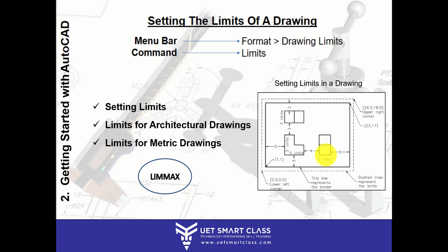Let me give you another example. Say you are drawing a 50 yards plan of a particular house or a flat. If you are drawing your other drawings for a 50 yards area, you know you have to make 4 elevations or 2 elevations, or some working drawings for it. Accordingly, you will set your drawing limits.